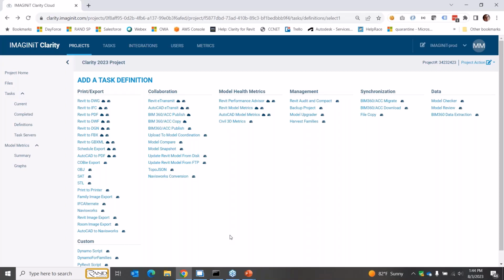I generally feel like the guidance that we've heard from Autodesk is that it's 20 times the size on disk. So that would say that 1 gigabyte size on disk means 20 gigabytes of RAM necessary. So I would generally say that total project size with cross-linking, being 1.3, 1.4, 1.5 gig is the place where I'd start getting very worried.